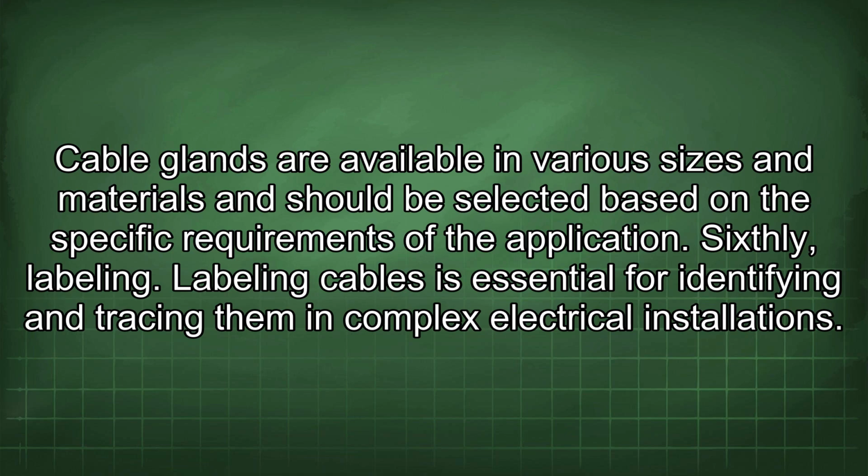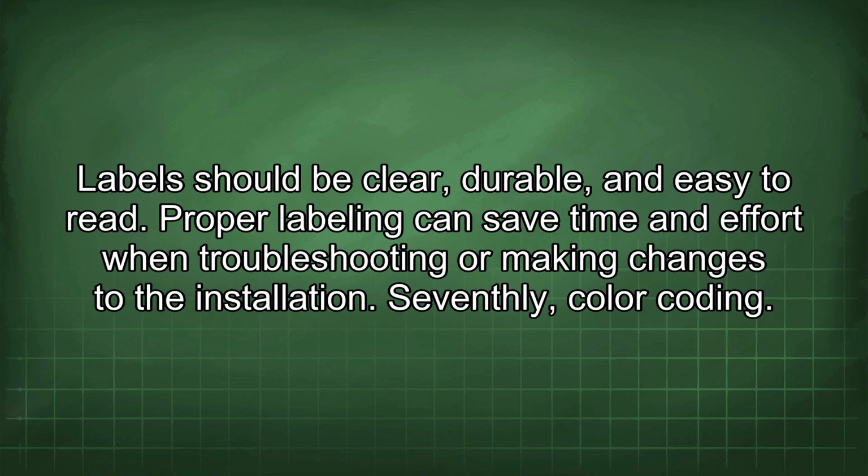Sixthly, labeling. Labeling cables is essential for identifying and tracing them in complex electrical installations. Labels should be clear, durable, and easy to read. Proper labeling can save time and effort when troubleshooting or making changes to the installation.